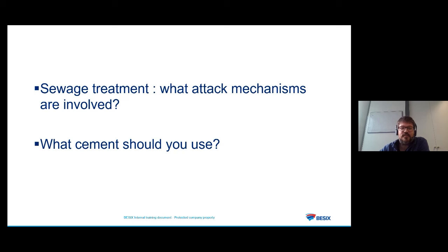Thank you. Sometimes I also just want to point this out. Sometimes we put epoxy painting on the rebar to protect the rebar directly. This is something that we try to avoid because you can have a lot of problems with that. You lose the bonding between the concrete and the rebar. As soon as, during the handling of the rebar, you always have a little bit of painting coming off. So it's something that we try to avoid as much as we can. But at least you know that it exists. Yeah, thank you. You're welcome.